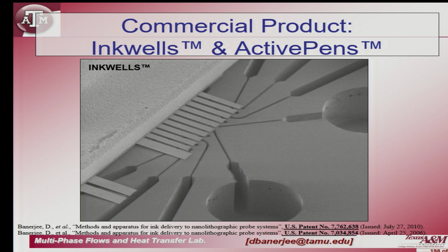The idea was to have capillary flow pump inks of different color from a big reservoir up here into these tiny wells over here. These wells are of the order of about 10 microns in diameter, and this channel that you see is of the order of 5 microns in width. So you can use a capillary or wicking mechanism to let the ink flow into each of these small wells, and these wells have the same pitch as the pitch of the tips on this cantilever. So you could go dip your tip, and each of these tips will have different colors, and then go and write. That was the whole idea.